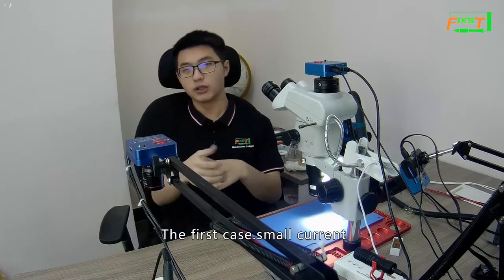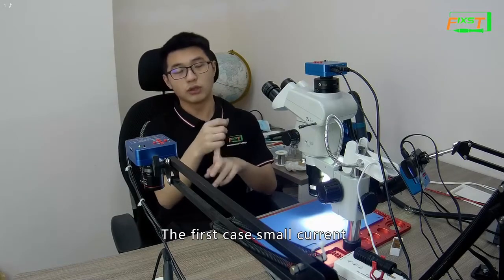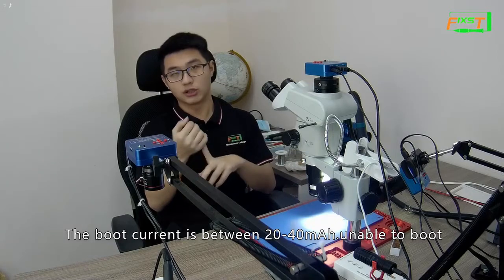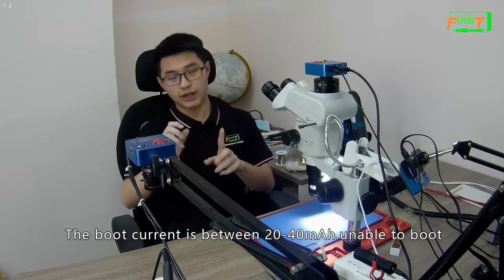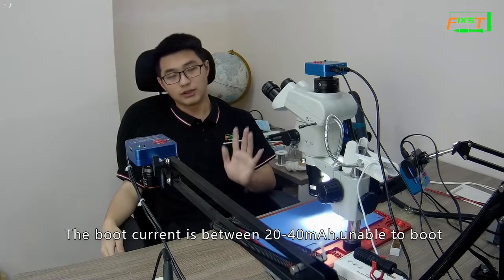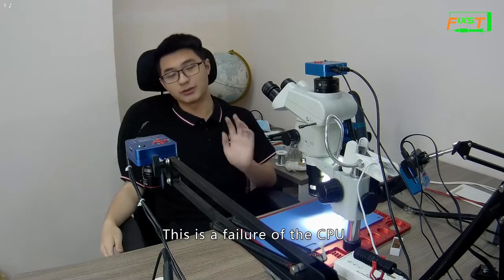The first case, small current. The boot current is between 20 to 40 mA, unable to boot. This is a failure of the CPU.